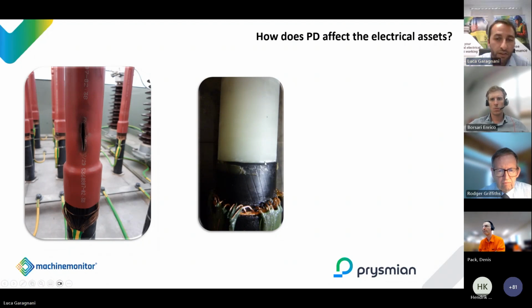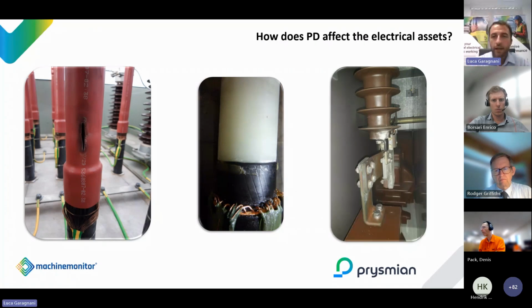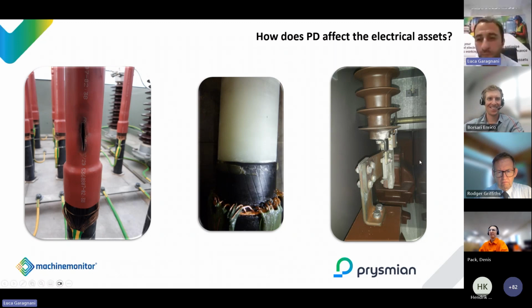No grading system means you have the electrical voltage line coming out here and generating a voltage stress on the surface of the XLPE that generates discharge. Different picture, different problem. I don't talk only about this surface discharge in the termination, which, by the way, we call interface, just to confuse a bit more, and it is a mix between surface and internal. So we call it interface.